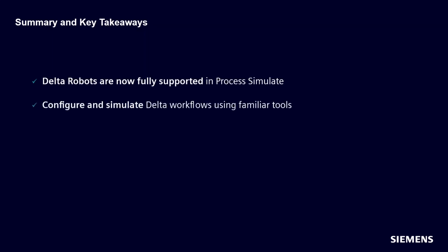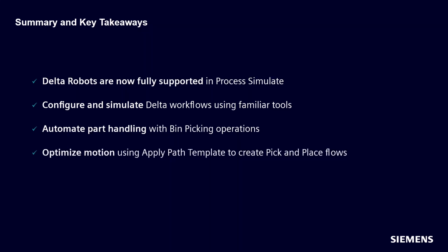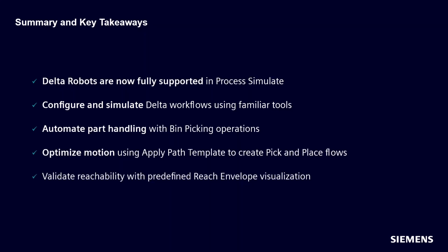In this demo we have shown Delta robots are now fully supported in Process Simulate. Configure and simulate Delta workflows using familiar tools. Automate part handling with bin picking operations. Optimize motion using Apply Path Template to create pick and place flows. Validate reachability with predefined reach envelope visualization.